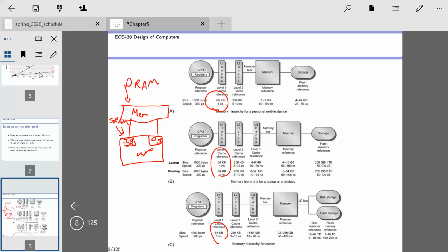So you might have sort of novel memory hierarchies, or maybe not novel per se, but custom memory hierarchies when you go to the embedded world. We found with our crypto code and what we were using our processor for, we could get by very well with a 4 kilobyte cache. And so 4 to 8 is what sometimes you'll see in the embedded world.